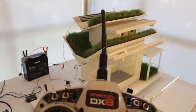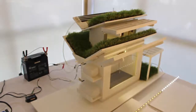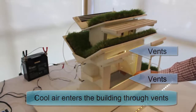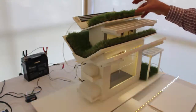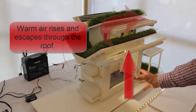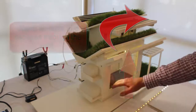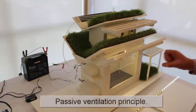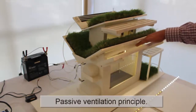Now the ideal would be to have some vents at the bottom here, an opening right there. So once you open the clerestory and the warm air escapes, cool air and fresh air would enter the building through the vents. That is a simple principle of passive ventilation. You can see some openings over there, specially provided for passive ventilation.